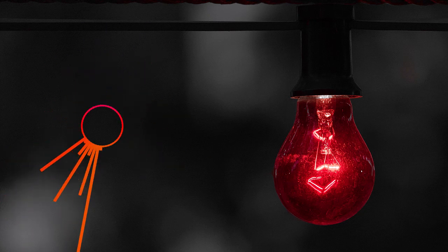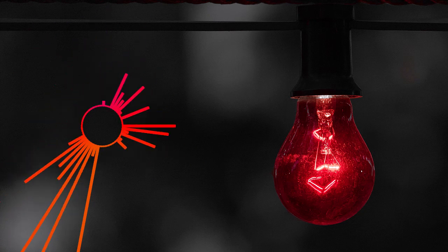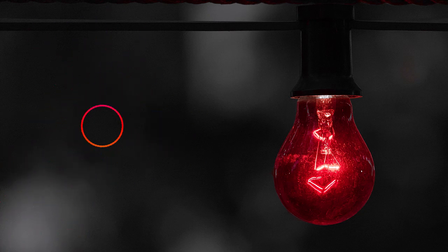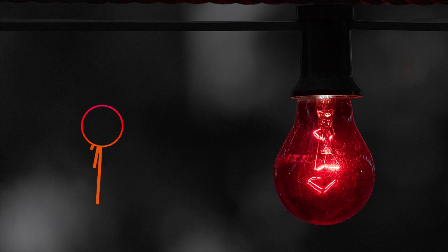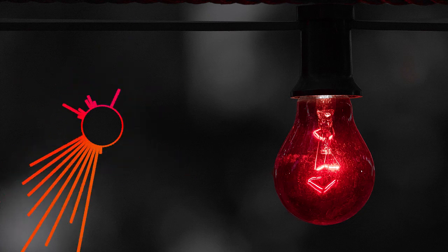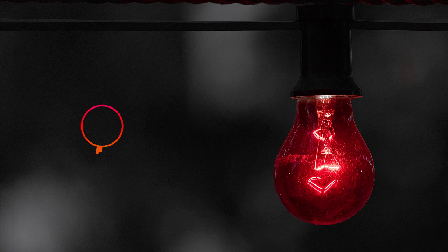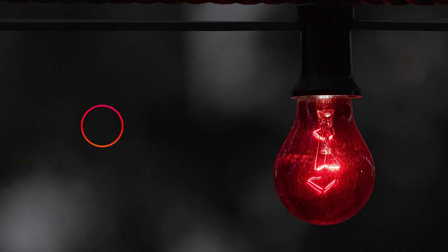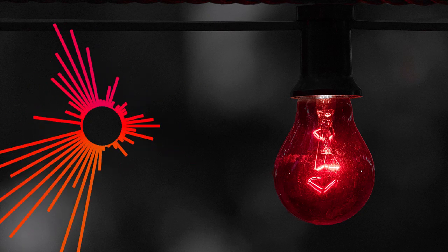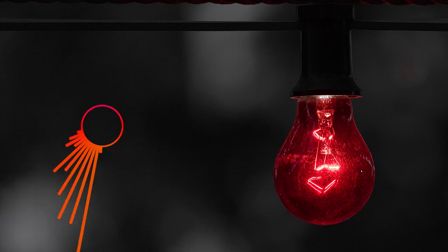Tip for electricians: you can layer lighting by using multiple switches. For example, one for overhead lights and another for accent lights. Next, we have key activated switches. These look like regular wall switches, but they require a key to operate. They are used in areas where only authorized people should be able to turn the lights on or off, like storage rooms, display areas, or restricted zones.